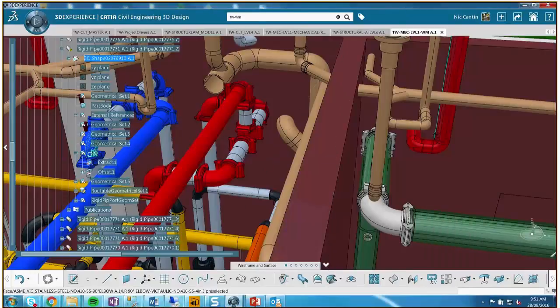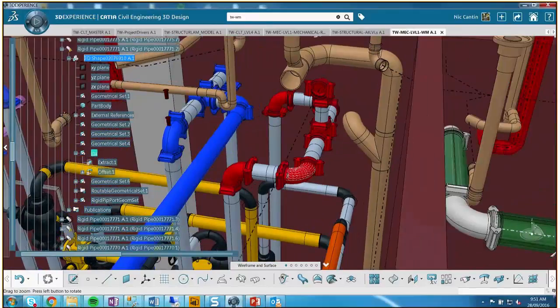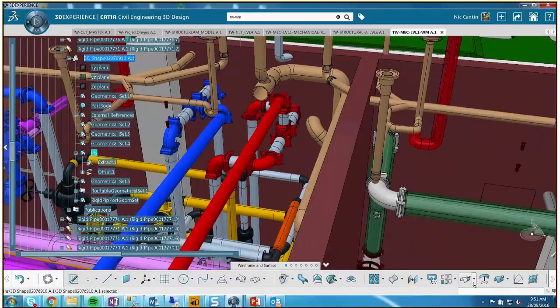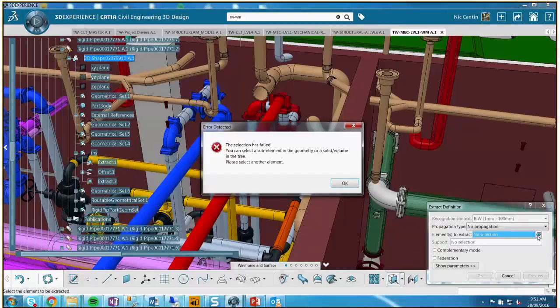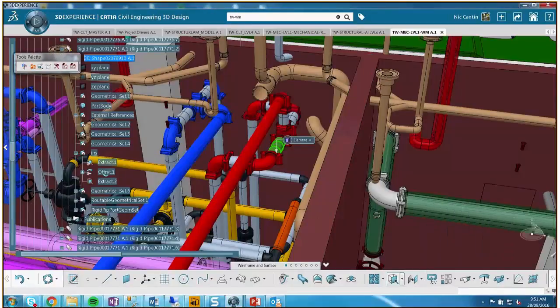and then we can use an offset surface to generate the insulation. So if you need insulation on any of your piping, I don't know if any of you are using piping or modeling that, it's a good way to quickly add an insulation thickness to your pipes, and it's nice because it's pretty much the same thing in terms of a visualization of that insulation part.